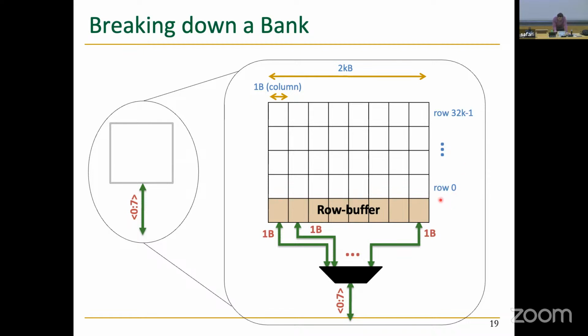That might be wrong, it could be 128, but it's not so important. You have what's called a row buffer. We didn't describe these structures yet, but this is an array of sense amplifiers that you have to go through to access data residing in your DRAM cells.